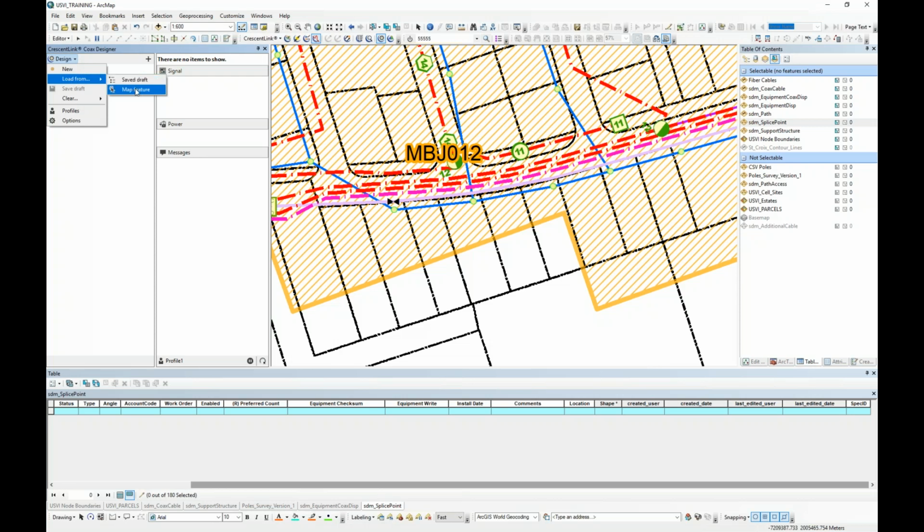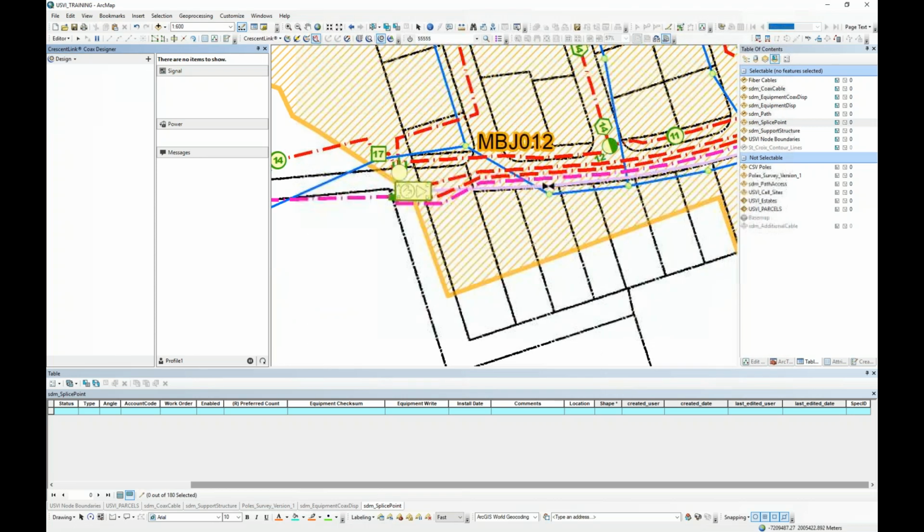Just to, with the way we design the HFC plant and stuff, this isn't really going to give you a real number of active customers. What it's going to give you is the number of homes passed, because we basically drop taps for vacant lots and stuff as well. Correct. Yeah. So you're not going to be able to use it as a direct correlation as far as how many customers do we have on a node at this particular time. True.